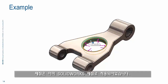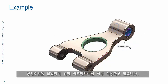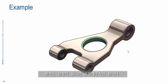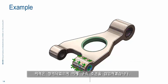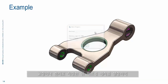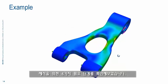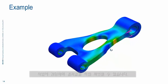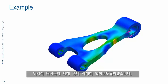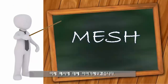So we have the material already, SOLIDWORKS material. We put down the force. I want to have it in the front here. And I use the geometry a lot to put my boundary conditions, choose directions if I want to. So now I put the force and I want to restrain it here, if it's going to be fixed or a hinge. And then we can mesh it real quickly here, and then we can run it. And these are the 4 steps that are needed to run a simulation. It is quite simple to do, and then we can look at the results. But we will go through all this in more detail now, all the steps, and see a little bit more what we can do to get a result.